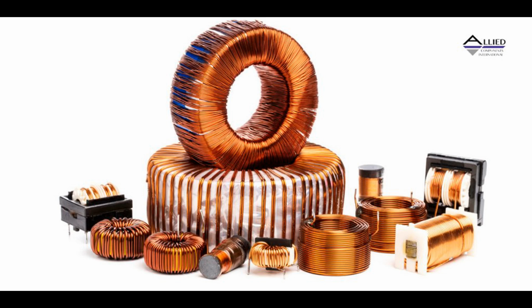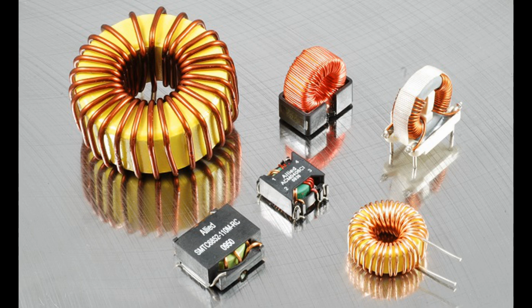Once the engine has warmed up, fuel vaporizes more easily, and the choke is gradually opened to allow more air into the engine, restoring the normal air-fuel mixture for efficient operation. Types of engine chokes. Manual choke.